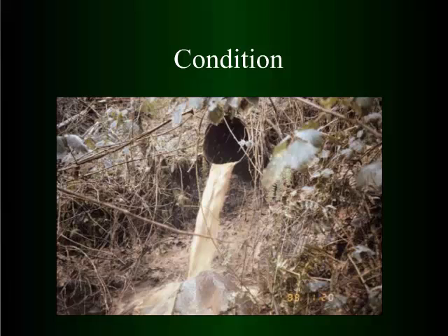On those, when we get further in there, you can use downspouts on them. You can armor them, put some rocks and some root wads down there, and give it something to kick off of. Basically, you want to dissipate the energy. Downspouts are a pretty easy method. You use a downspout long enough to get it off the toe of the fill, get it down to native soil.